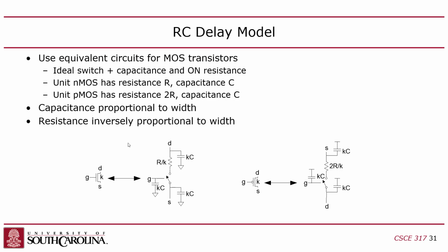It doesn't do anything. It doesn't hurt me because it's not a very good capacitor when both sides are connected to VDD. However, the other side, though, is a problem, right? Which is the source, or the drain, actually. Yeah, this is the source. The source is the top and the drain is the bottom on the PMOS. I don't know why they have it swapped with that one. But anyway, it doesn't matter because it's just convention. The source and drain are interchangeable here. But typically the source is VDD on PMOS and source is ground on NMOS, but it's not that important. Okay, so the point here is that only one of these guys actually hurts me, but that's only because it's an inverter.